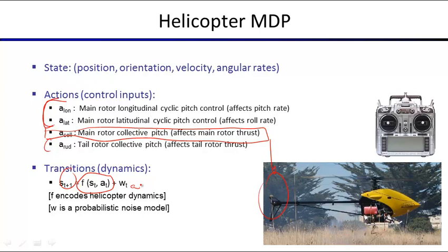But after executing the first one in the sequence, we would say, oh, with all this noise, not so sure that we should keep executing what we computed in the beginning. So let's recompute, rerun a search to find the best sequence of controls from now onwards. And you keep repeating this search after every step. So it's continuous replanning after every step. In practice, for this helicopter, every 1/20th of a second, it would replan a 2-second look ahead.